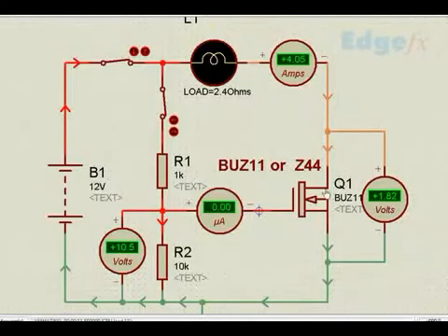This is because the RDS remains constant, and when the current of 4 ampere flows, the voltage drop is this. You can calculate RDS from this also. Like for example, this voltage divided by this current will give you the value of RDS. Though you are not required to calculate the value of RDS, RDS is specified by the manufacturer. The same situation you see: the current flowing is 4 amperes, voltage drop is 1.82 volts.